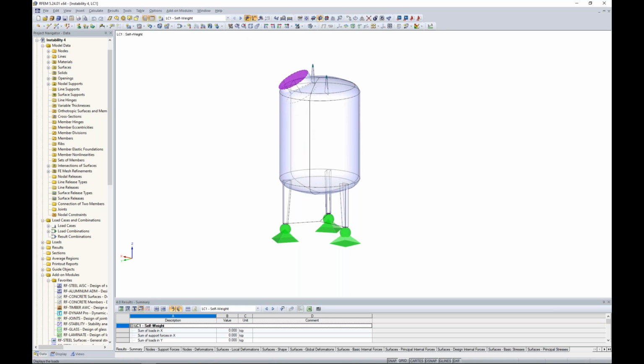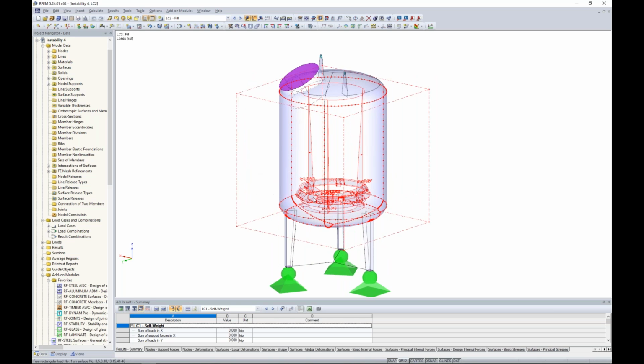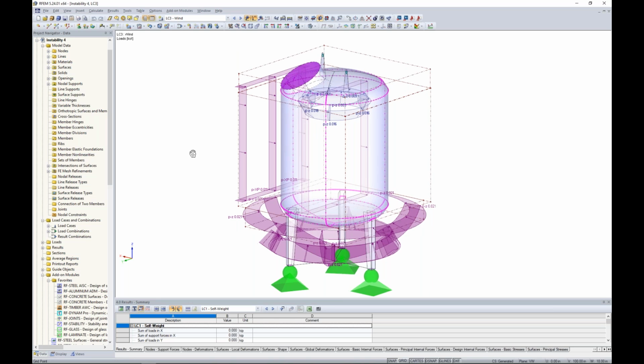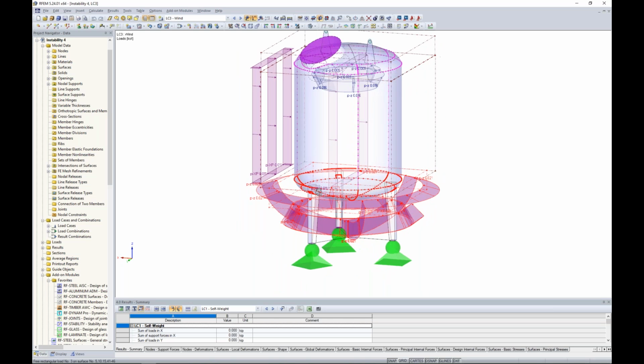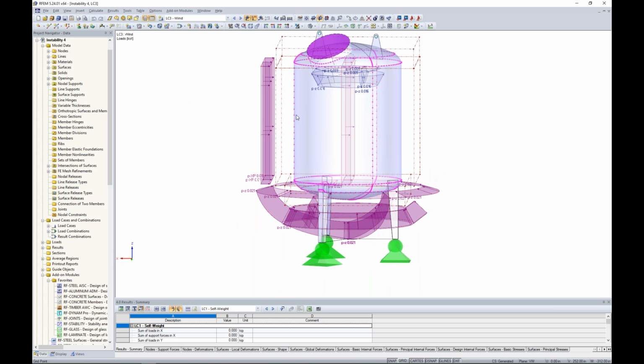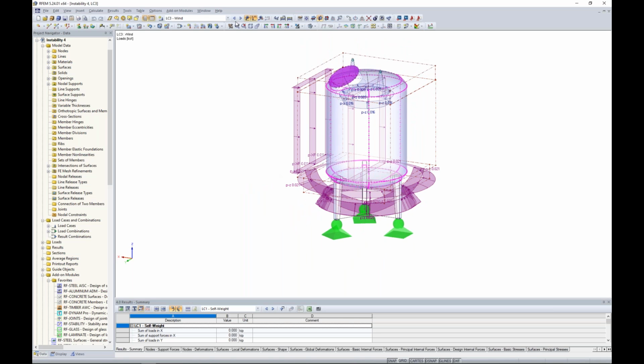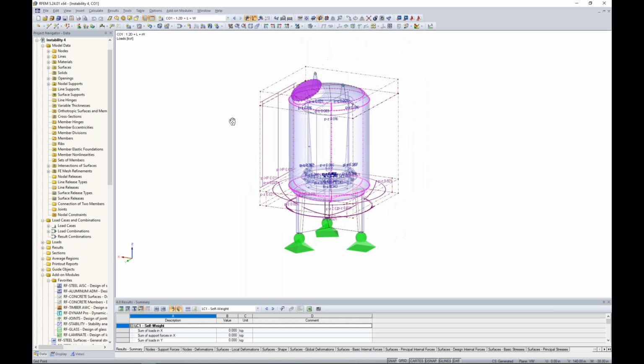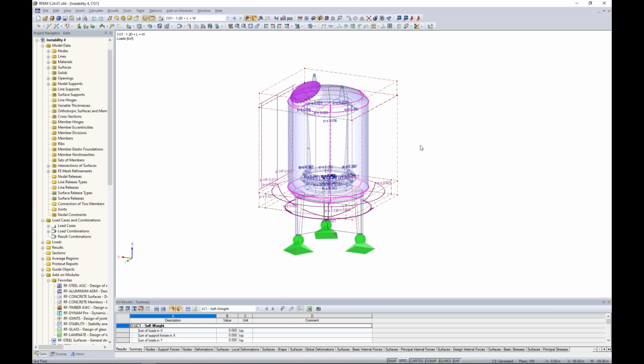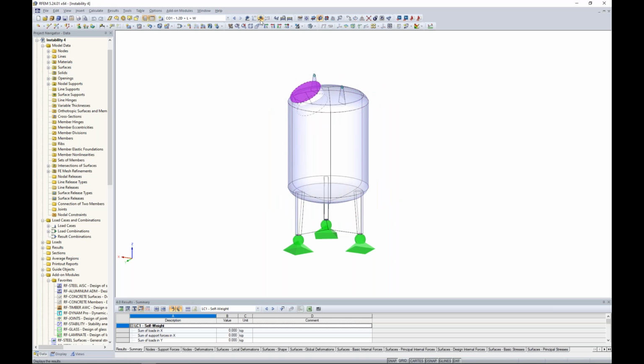So when I take a look at my applied loads, we have our first load case, which is just self-weight, so no additional loads are shown here. Then we have our fill load. So this is going to be an internal load kind of pushing out on the structure walls here. And we have a wind load, which includes an uplift from the bottom and also a lateral load coming from the left with a suction force over on the right-hand side. So taking a look at my load combination where I've applied all three of these load cases together, we'd like to begin our first analysis.